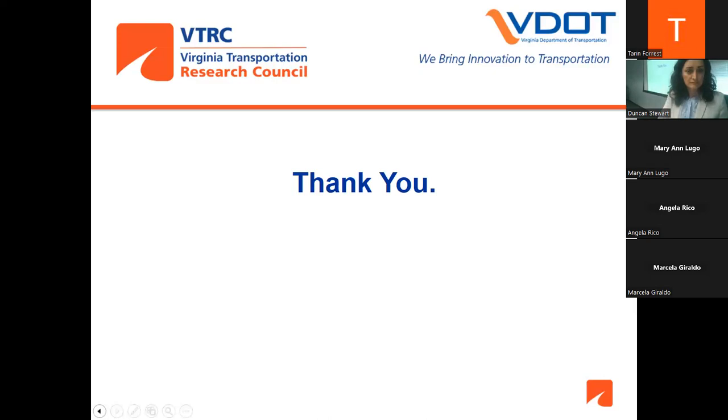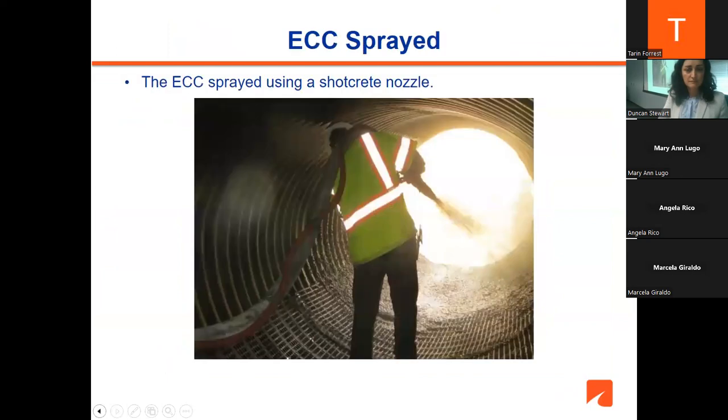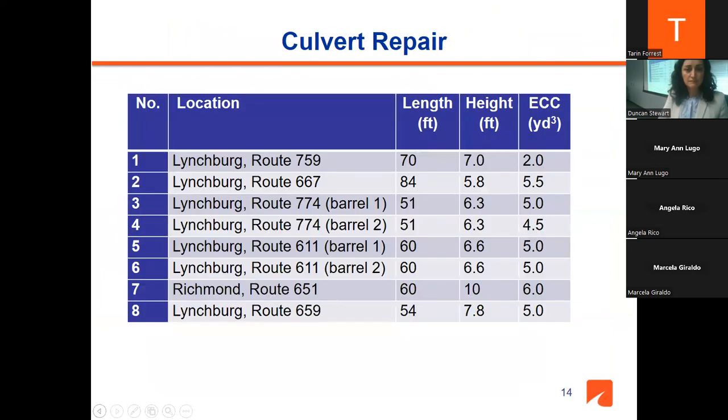In fact, the first one we did had an asphalt lining. You know that concrete doesn't bond to asphalt that well. So in our meeting I asked them, can you please remove this asphalt coating so we can repair the culvert? They said it's cheaper to replace the whole culvert. They didn't want to get into cleaning or replacing the asphalt. So we said okay, then we'll go and put it in. We put it in a 6-foot section, like Mary was explaining, and then the question came, is it working? A few months later, we were talking about how we would know if it's working or not.